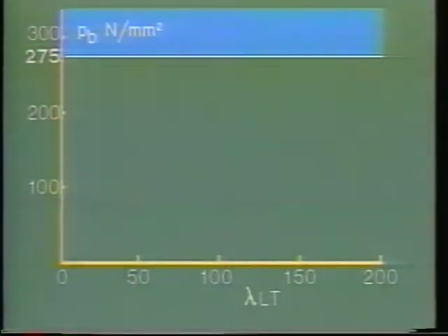In terms of extreme fibre stress, this behaviour plots as a line which has a very low value when the slenderness is high, but has a very high value when the slenderness is low. This line, too, is an upper bound to the actual bending strength. For low slenderness material, strength is the limiting condition.